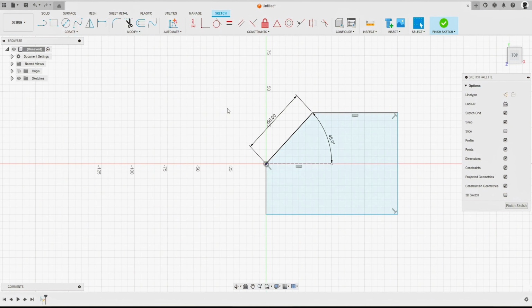We're free to use any other tools. So now we've created a basic sketch. If we then look at the color of these lines, we can see this one is black, this one is black. The other two lines here are both blue, and that indicates that they can move. Okay, so we can move this line like so on the x-axis, and this one on the y-axis. And we want to constrain those in place. But to do that, we want to apply dimensions.